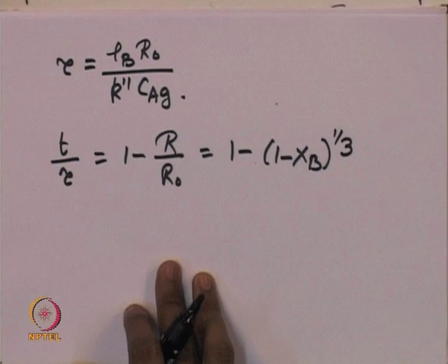So, now we looked at 3 particular cases of the relationship between fractional time and conversion if the system is diffusion controlling through the gas film, diffusion controlling through the ash layer, or reaction controlling, all for a case where the particle size does not change. That is when the reaction occurs, an ash layer is formed, where the ash layer may contain inert solids or the products which may firmly bind to the layer where the solids have already reacted.